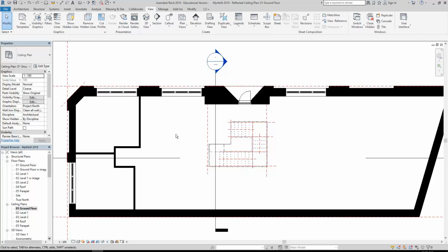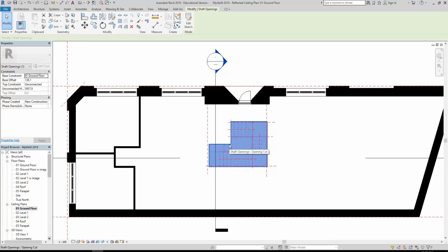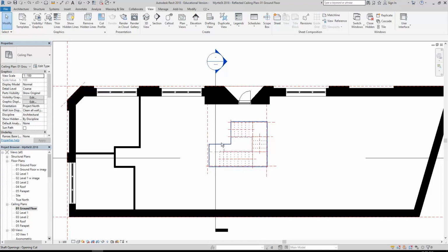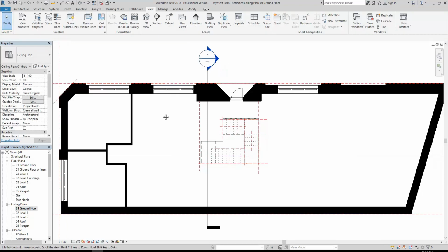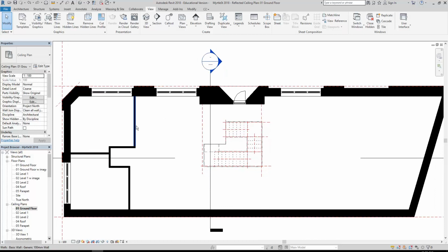Okay, so I've got my ground floor ceiling plan, which is going to show my ceiling. I know it will, but it's not very clear that the ceiling's there. So I'll just show you one little thing. If you want to find the ceiling in a floor plan, sorry, a reflected ceiling plan, do you remember the option key in Revit? Tab. So the option key is tab, and so if I move to the edge of the wall,